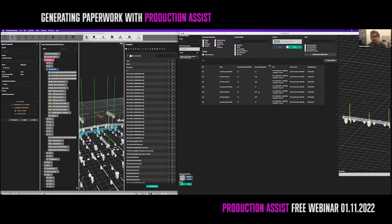I also see the current consumption in here so that I can have a look at how much power they actually need. If I need to turn this fixture on and off, it lists me the next fuse in line. So the next fuse for this, in order to turn this specific fixture on and off, is inside the VT1 onsite, fuse 3.1.